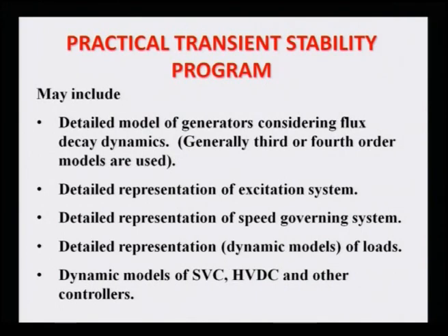For any practical transient stability program, whether it is for AC, DC, or both AC/DC, we have to include the various components that are involved in transient stability. That may include the detailed model of the generator considering the flux decay dynamics. Generally, third or fourth order models are used.